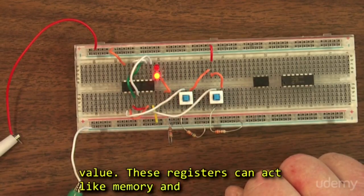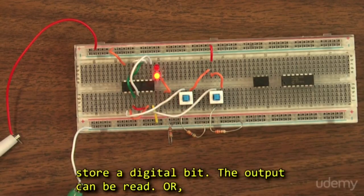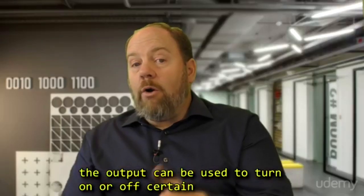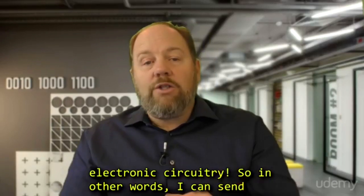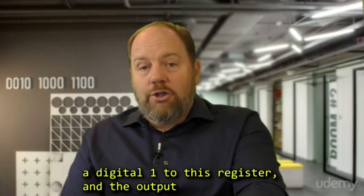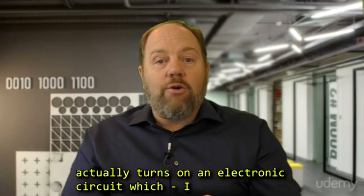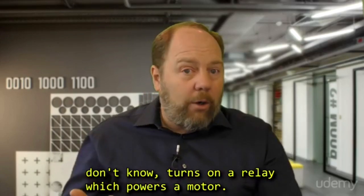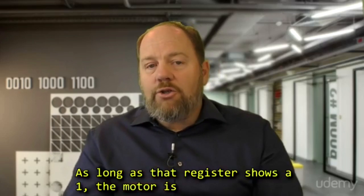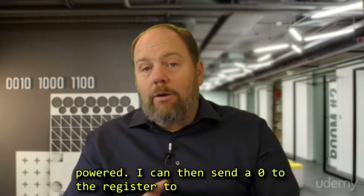These registers can act like memory and store a digital bit. The output can be read, or the output can be used to turn on or off certain electronic circuitry. So in other words, I can send a digital 1 to this register, and the output actually turns on an electronic circuit which, I don't know, turns on a relay which powers a motor. As long as that register shows a 1, the motor is powered.